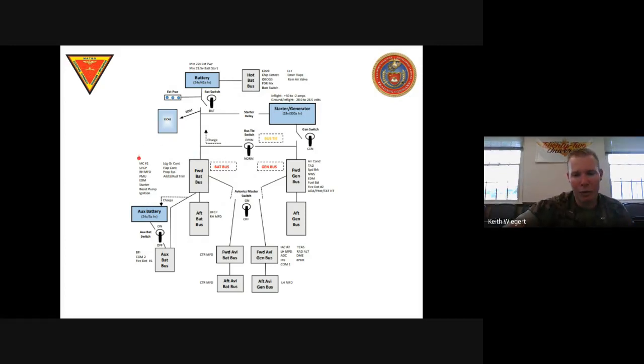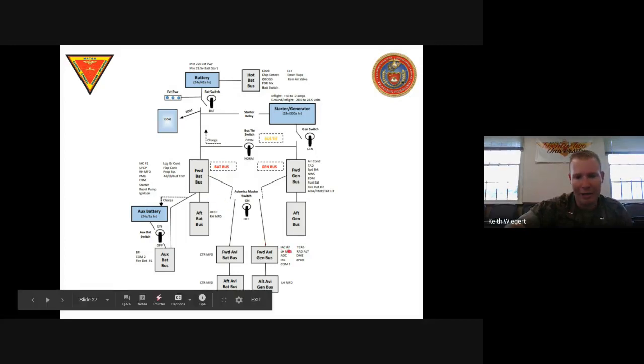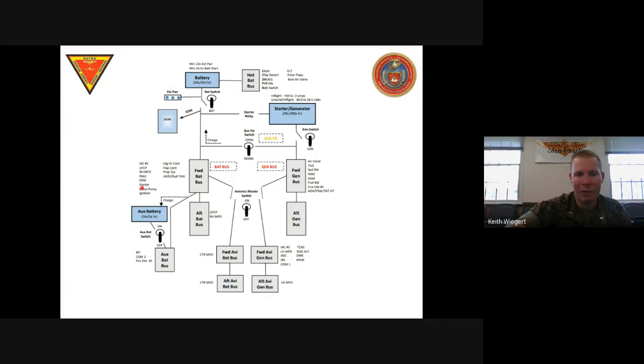So you've got IAC number 1. This is your integrated avionics computer, right? This basically runs your bank of MFDs in the front cockpit, runs all your computers. Your instructor has IAC number 2 that runs the rear cockpit, but they can repeat off of each other so that if IAC number 1 fails, then you can use IAC number 2 to run the front cockpit and the rear cockpit, right? That's kind of how this guy works.